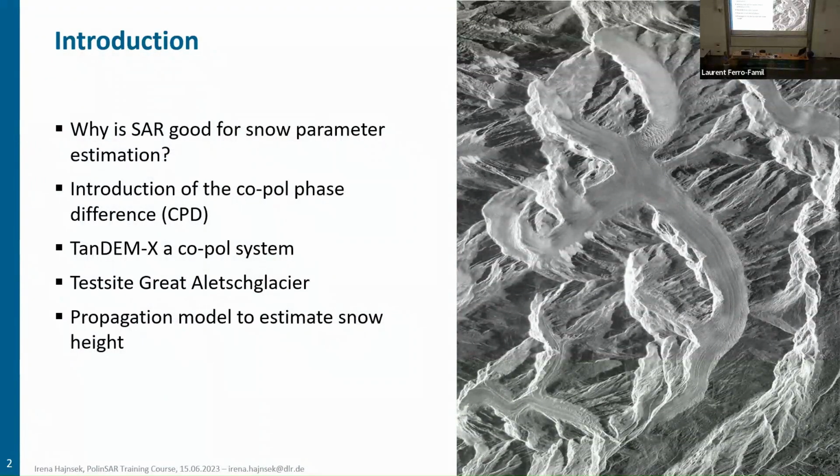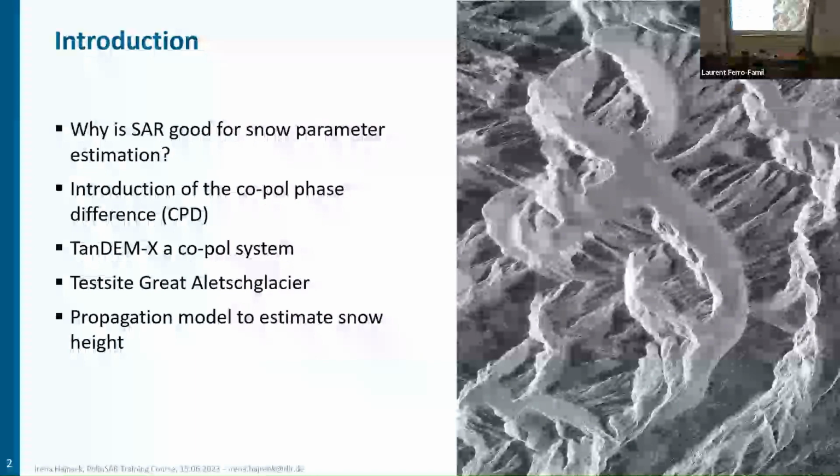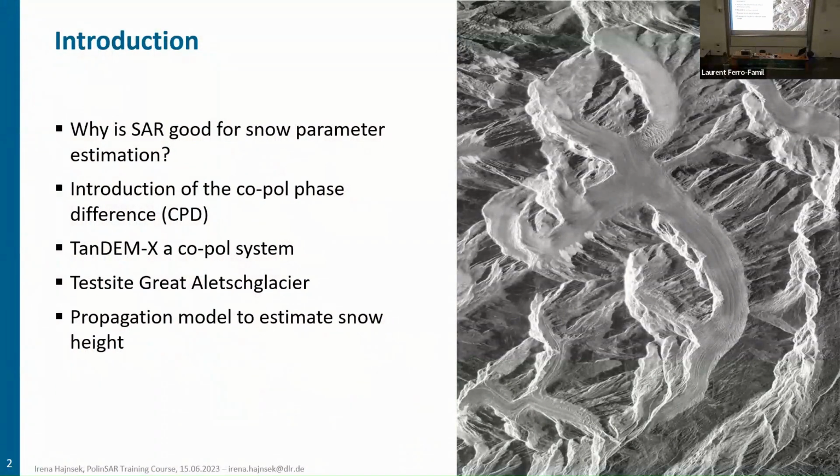And like this, you can identify from where the satellite was flying. So from where was the satellite flying now? Yes, from this side, right? So the satellite was flying here. From this side, it was illuminating this area. And then we see the peaks here are kind of overlaid, or closer. I mean, the peak is closer to the sensor. So therefore, what you have normally is a foreshortening, so the signal is shorter. And everything that is negative, on the other side of the mountain, is a little bit stretched, as you can see here, very strongly stretched, and you get less information back, right? Because the whole energy is really coming from the peaks of the mountain towards the satellite.